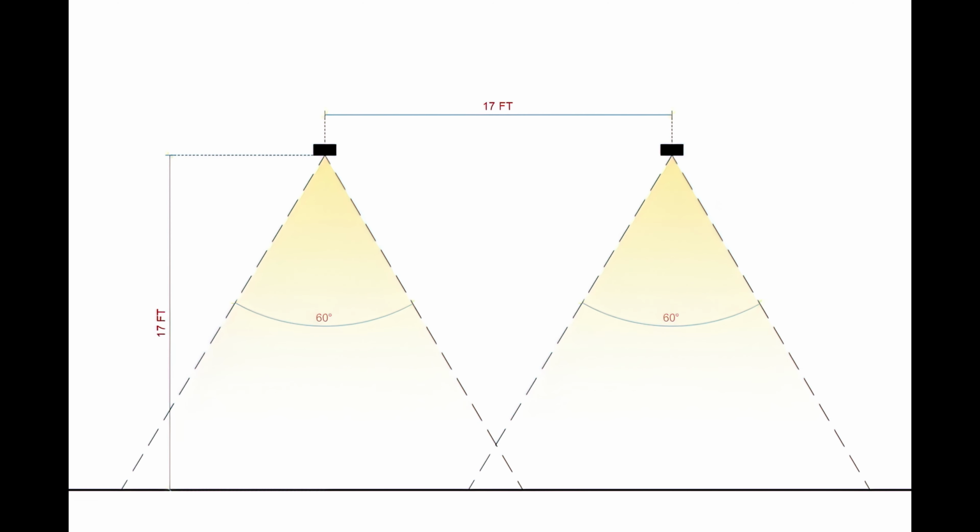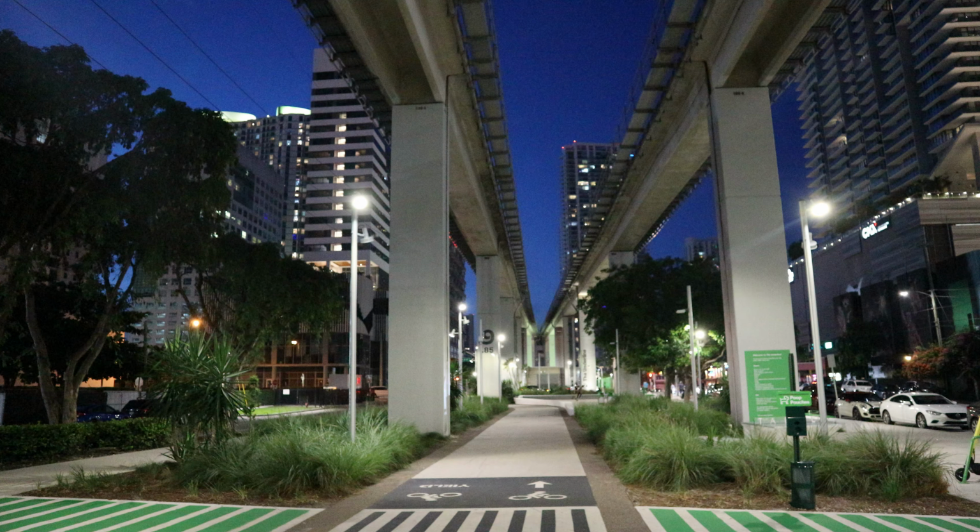In our second try, we chose a symmetric wide fluid beam angle with 60 degrees. As you can see, it covers all the area. One advantage we have with uniformity is we don't need high luminous flux, because our eyes are going to adapt to the uniformity of the luminance around. To understand this term better, let's review a few of the basic terms of lighting technology.